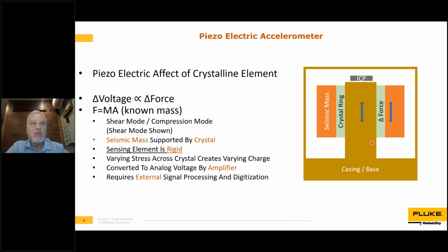Talking a little bit about their function, the piezoelectric effect of the crystalline gives you a proportionality with the voltage output. Again, these do output in voltage mode, and most of them have some sort of amplifier built into the package, but it gives you a voltage proportional to force. Then it's a simple calculation of force equals mass times acceleration. In this case, we have a known seismic mass in those accelerometers. That combined with whatever amplification the internal electronics gives you is the calibrated output of that device.